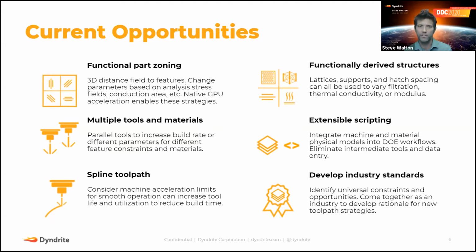The performance of this solution will allow us to do things like functional part zoning. We are starting to add, and in many cases, similar to SLM talked about, multiple tools in the build zone. And in some cases, we're moving to multiple materials in the build zone, either to increase build rate or change parameters, or again, change materials. We're looking forward towards spline toolpaths. Let's consider the machine acceleration limits in the toolpath design to both increase tool life,